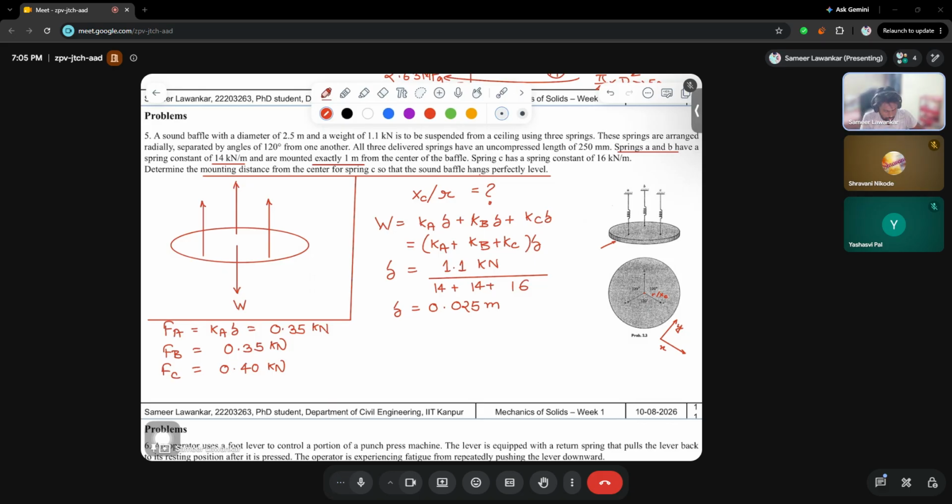So the moment due to weight is negligible, meaning it is not present, because we are calculating the moment from the center point. The complete moments will be the summation of forces from all three different directions. The point is that we need to calculate it along the length, which is the x direction here.